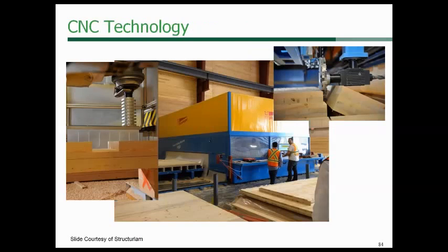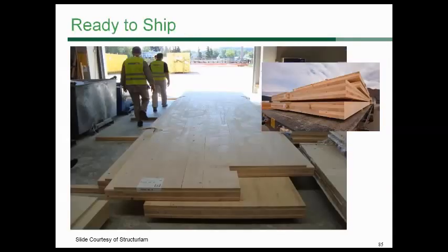In terms of cutting these things, CNC is a wonderful tool and allows you to do some really neat things with these panels. So you can have all of your window openings, your door openings, electrical chases, slots for connections. All these can be cut in prior to the panels being shipped from the manufacturer. So you can have everything cut out as you need it, which will reduce your on-site construction time. So you can see what the panels look like when they're ready to ship.